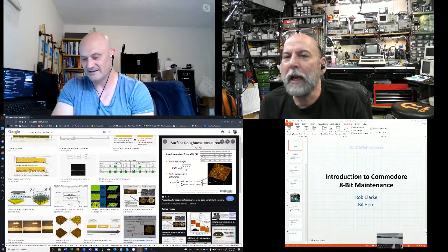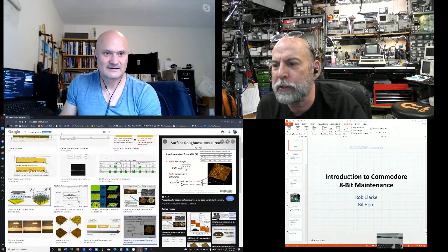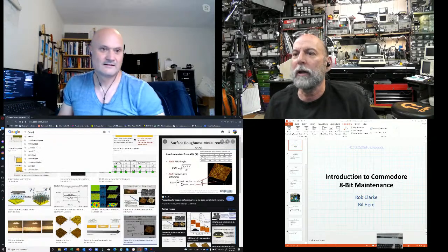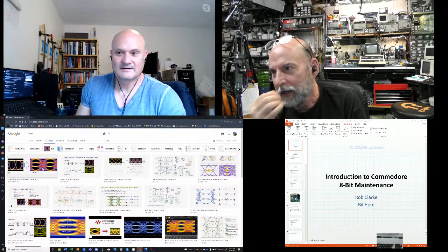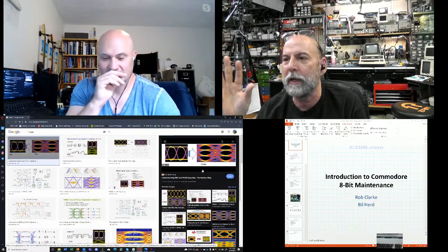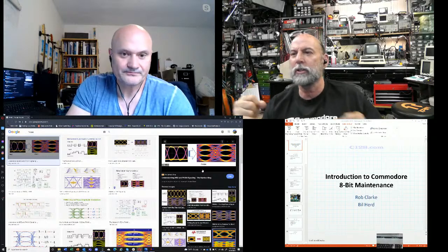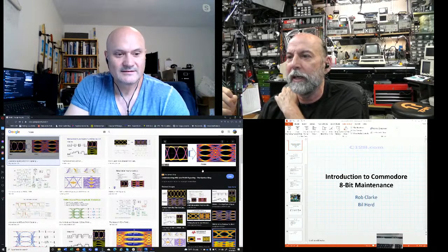So right. And that example on the C128 where we added the wire, I suspect that probably the segment was ringing. It probably wasn't just a single reflection. It was probably ringing up and down because in theory there should have still been like 15 nanoseconds for the ringing to die down, which is just forever. Yeah. And yet it was still active 15 nanoseconds later.